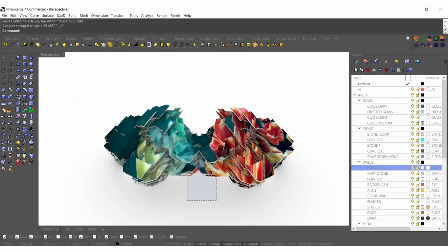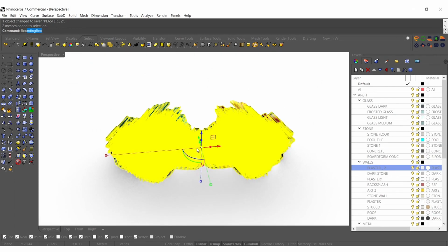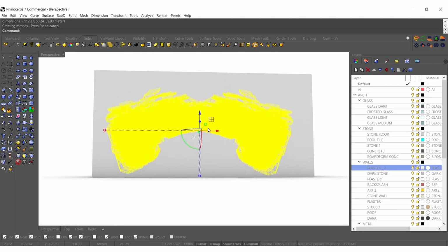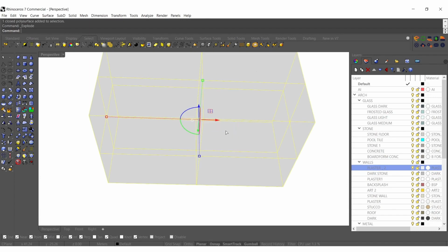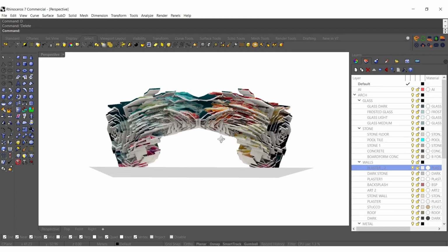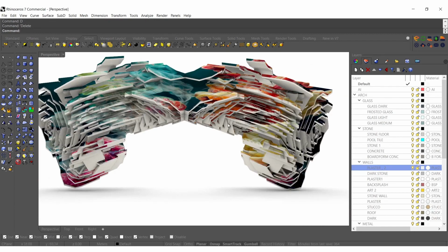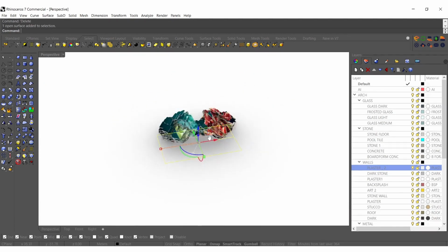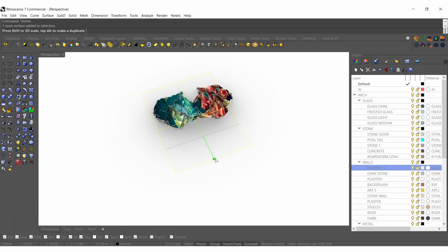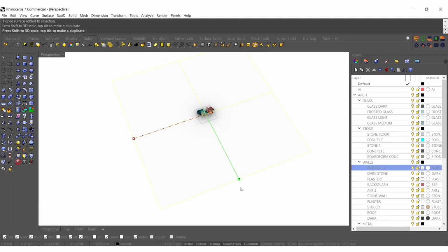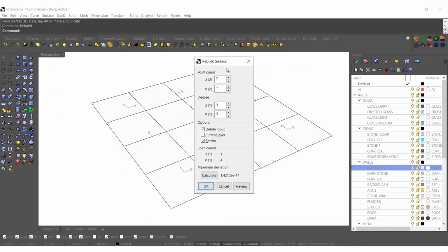Okay, go ahead and build our landscape. As usual, type in bounding box. I'm gonna lock down our model. And this particular one, let's do like a desert scene, I suppose. Maybe some water in the middle of the desert or something. Okay, so I'm just gonna bring this out. Okay, we'll rebuild the surface. I'm gonna say 75 points by 75 points.